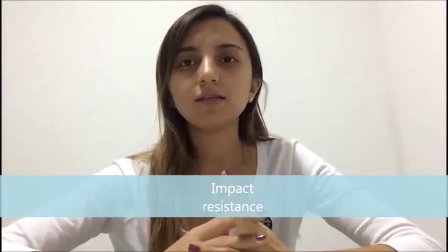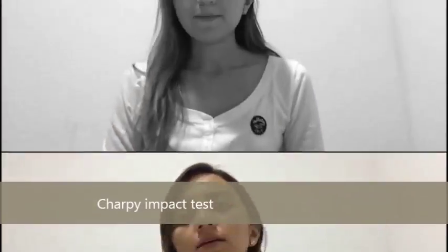Impact resistance is called the resistance of a member or assembly to dynamic loading. It also refers specifically to an insulation's ability to withstand damage or abuse. Charpy impact testing involves striking a standard notched specimen with a controlled weight pendulum that is swung from a set height. Charpy tests show whether a metal can be classified as being either brittle or ductile.